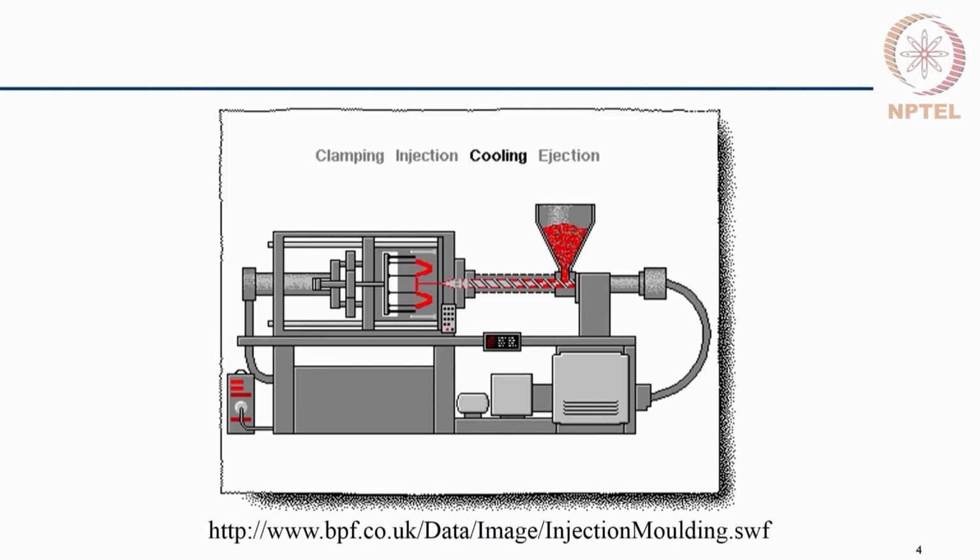So, the injection molding process consists of about 4 stages. The mold, which confines the material to the part geometry, is made from the part drawing, and the mold is manufactured and clamped using the machine. There is a movable part of the mold and a fixed part on the side from which the injection takes place. So, you can see that this is the moving component and this is the fixed part of the mold,